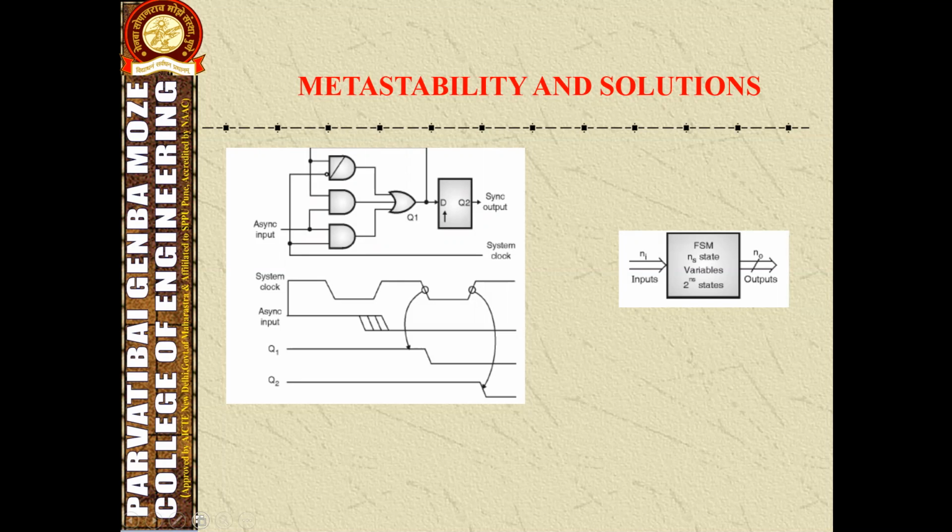Therefore, the probability of failure becomes small and the MTBF of the digital device improves. While using the measurement setup above, the designer gets K1 equal to 3 into 10^46 and K2 equal to 0.05 nanosecond with a gated latch.